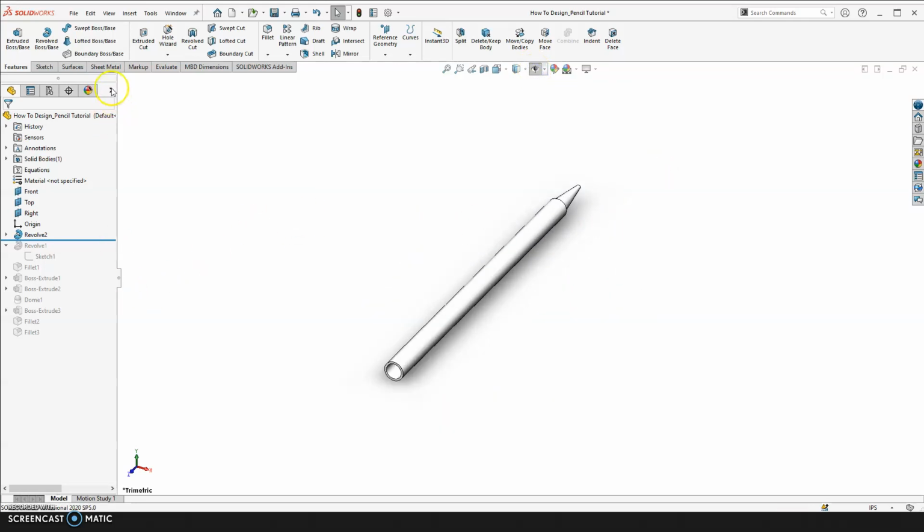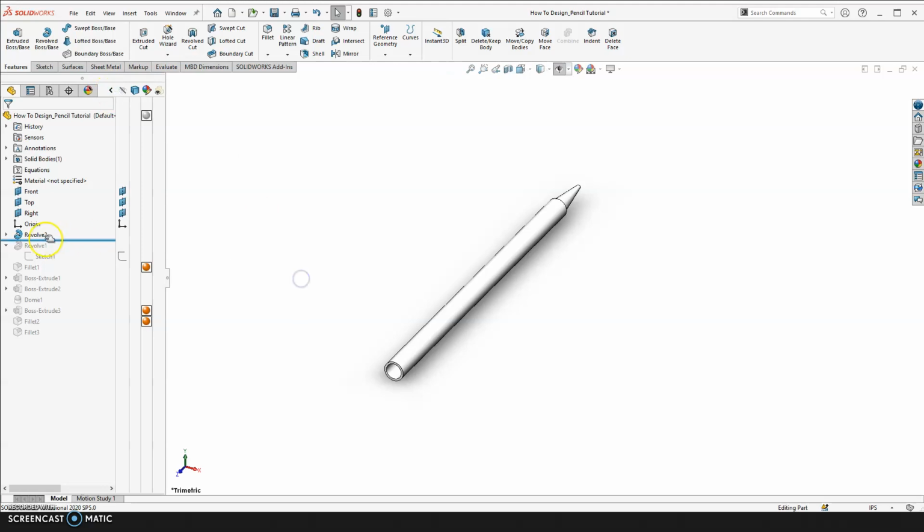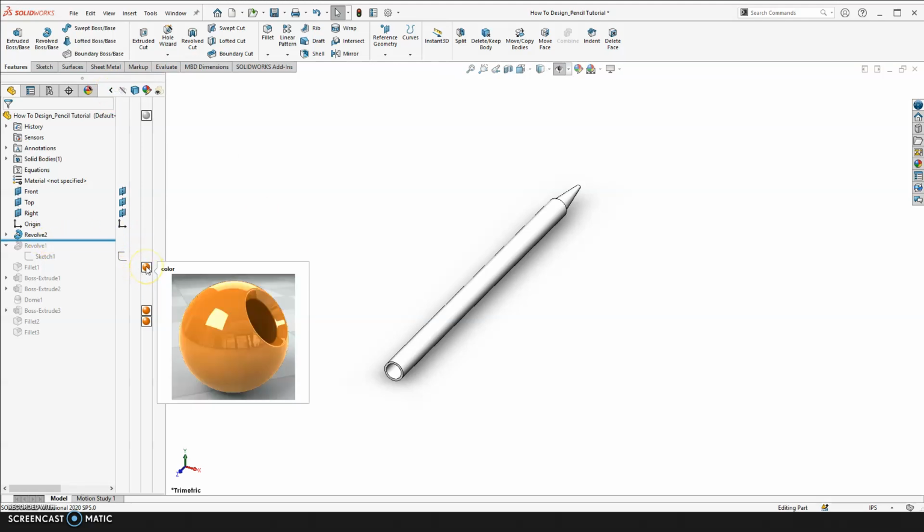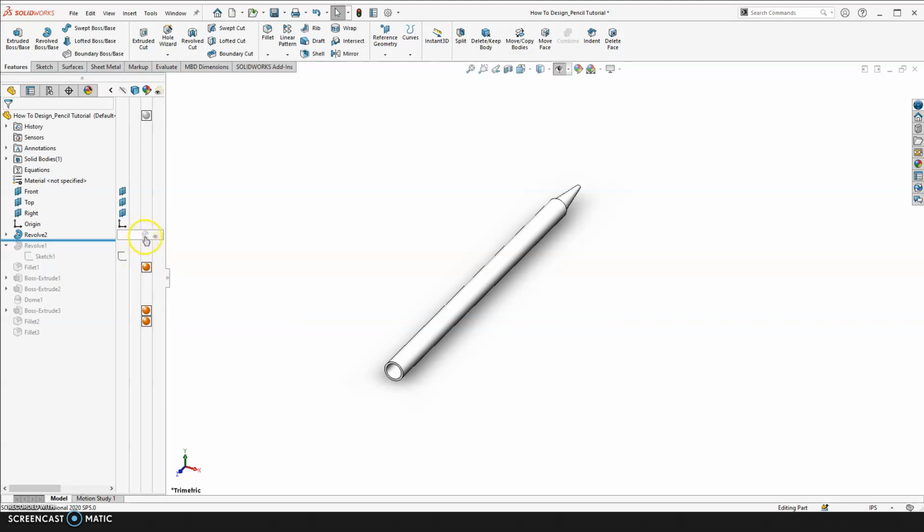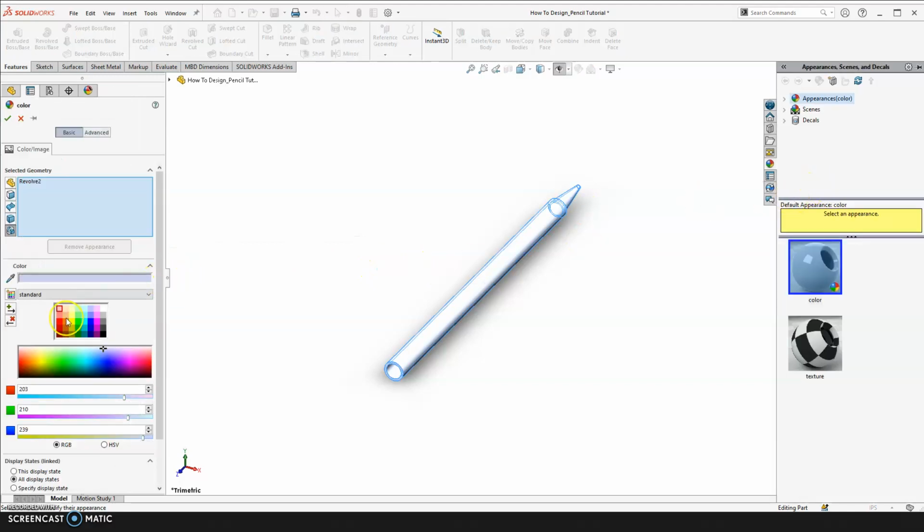Now, what I can do is click on this arrow button here, and I can copy the colors I've already assigned before, but I'll show you how I did that. Just go ahead and click here, click on this option, and go up here, do a select face, and choose a color you want, right?